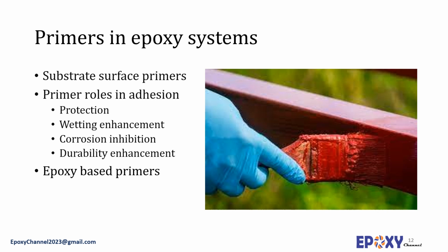Finally, primers, in particular organosilane-based primers, may result in durability enhancements and interfacial stability in the presence of moisture. Epoxy zinc-rich primers have also been produced for corrosion inhibition in steel structures, which contain zinc dust as an active ingredient. These systems can be applied similar to other conventional primers.